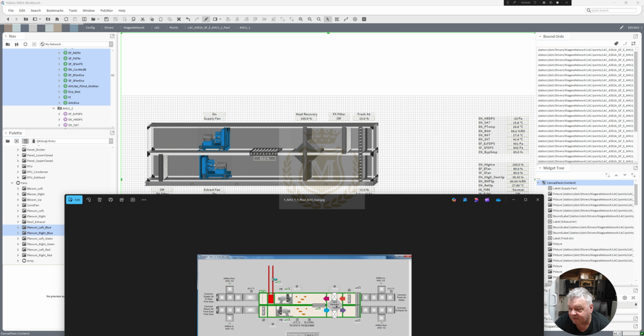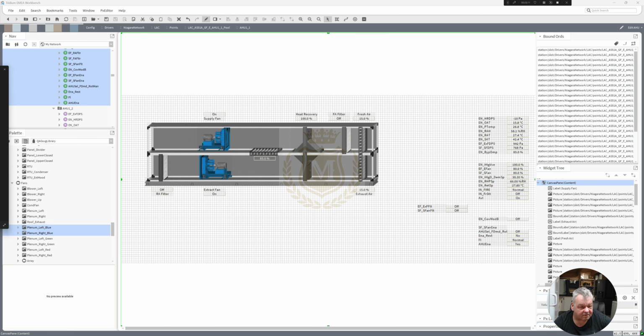We've done that bit, we've done the heat recovery, we've done the filter, we've done that filter. We've got a frost to put in there, and we've got a heater battery to put in there. And maybe we stick some more ducting across what they've done there, because that's probably common exhaust air, AHU flow from. So I think we need to stick them in there and put some more ducting in there, which is fine. So we need the heater battery.